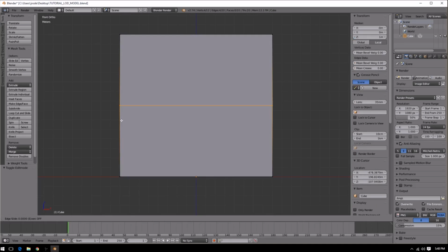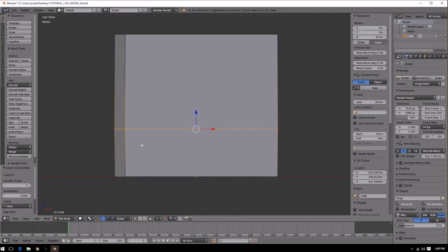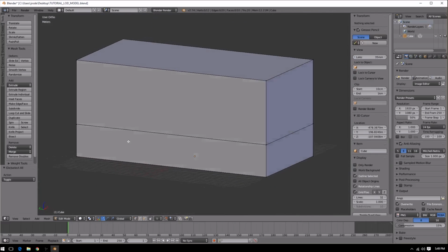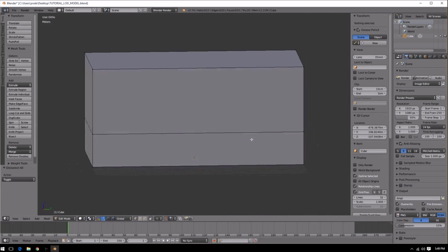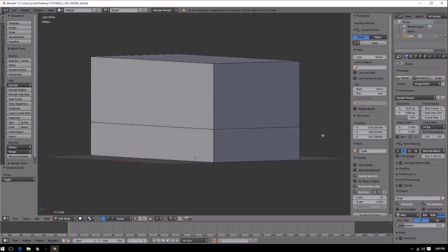And once you click it once and only once, then you can actually move this loop cut up and down depending on where you want it. Now notice that it's snapping. I still have snapping on, and it's not snapping to my lines directly. So I'm going to hold Shift and scroll this up so that it snaps directly to where I want it to. Boom. And now we're at the 5 unit mark. 2, 4, 5. So this floor is now 5 units high. And if you look all around our mesh, that loop cut tool just made a complete cut all around.